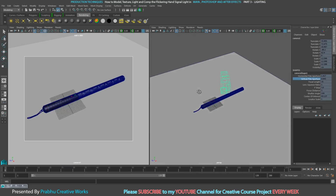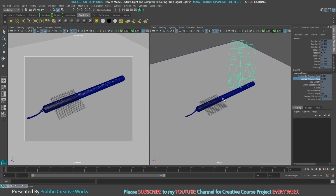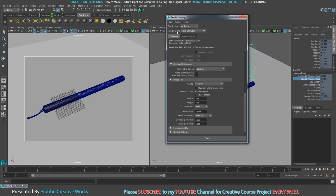Now we want to set our light. Before that, we want to turn on mental ray. So mental ray is our render engine for this scene, because I have some bounce light coming over this LED part. So I want to set my render engine as mental ray. So go to render settings and go to render using and choose mental ray.